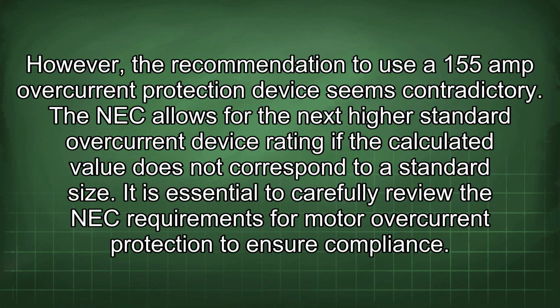However, the recommendation to use a 155 amp overcurrent protection device seems contradictory. The NEC allows for the next highest standard overcurrent device rating if the calculated value does not correspond to a standard size. It is essential to carefully review the NEC requirements for motor overcurrent protection to ensure compliance.